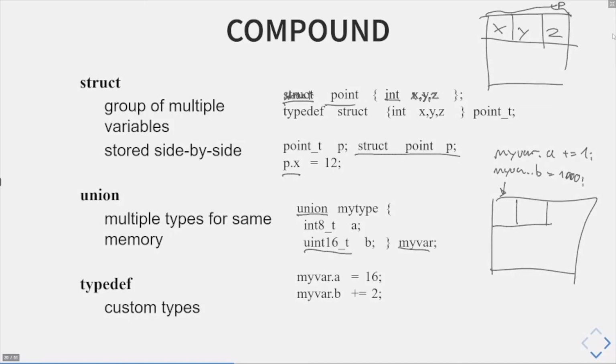A more common use case is basically if you have a binary interpretation, if you transfer something from it and the actual interpretation of this one. So let's say we get a sensor value from one of the sensors that I mentioned last time. So from this Bosch sensor, right? What we can do is to read out the registers of this file. If you remember, there was a 16-bit value for the temperature reading, for example.